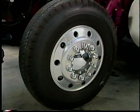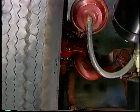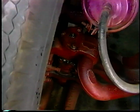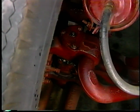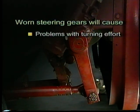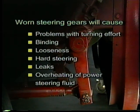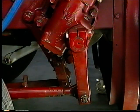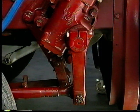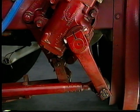If the concern for looseness or binding is not in the steering column, then check the linkage, kingpins, kingpin bearings and caster before condemning the steering gear. This is particularly true if the concern is for a steering wheel that is off-center or does not return to center after a turn. Worn steering gears will cause problems with turning effort, binding, looseness, hard steering, leaks, and overheating of the power steering fluid. Always check the adjustment of the gear when troubleshooting concerns of loose or binding steering. Beyond that adjustment, the gear will have to be removed and disassembled for further diagnosis.